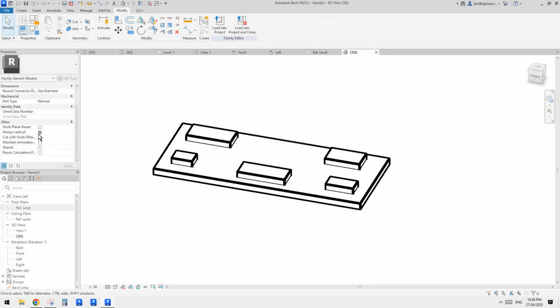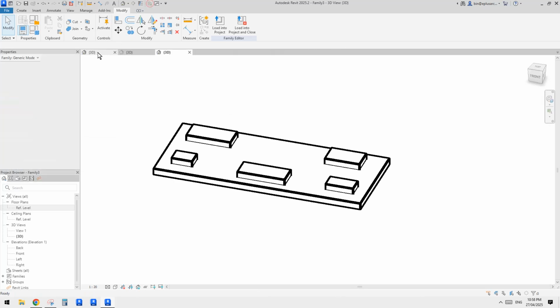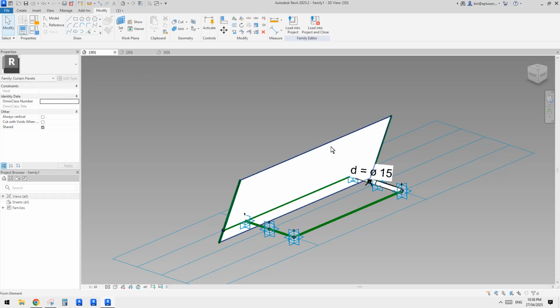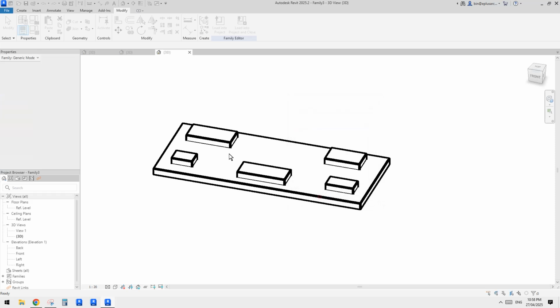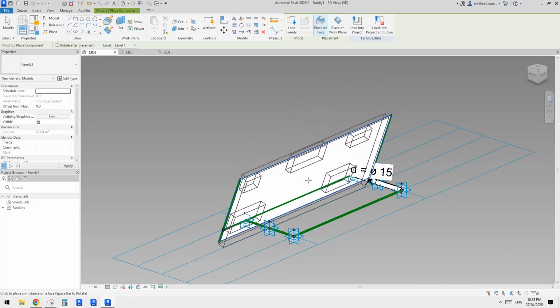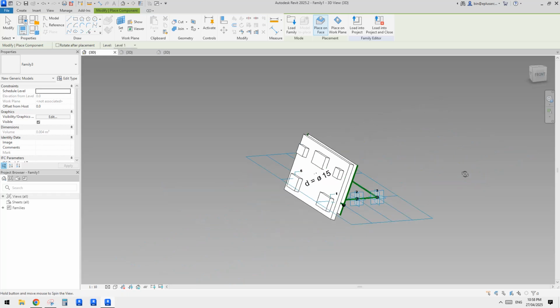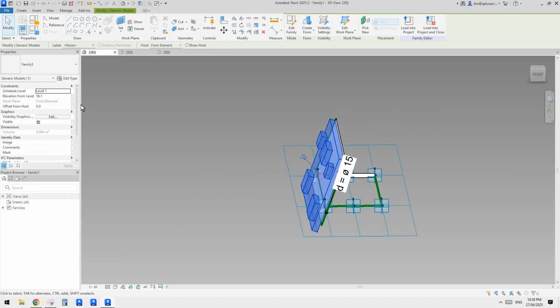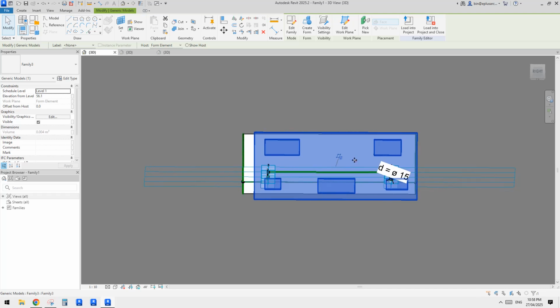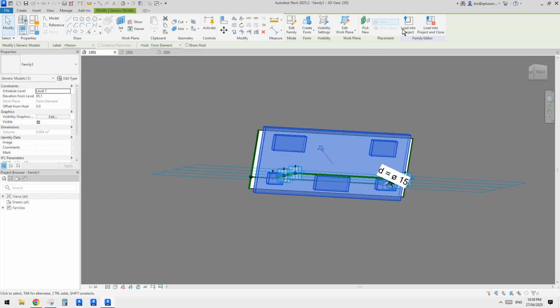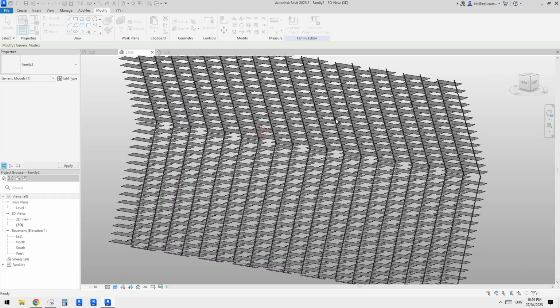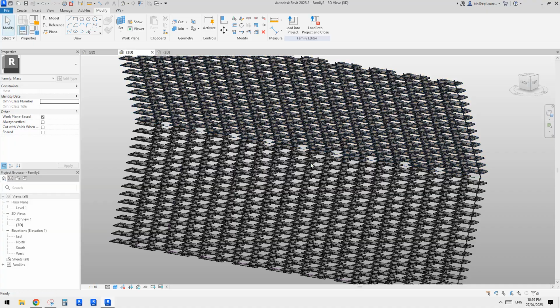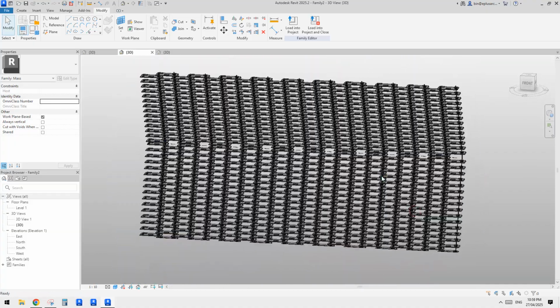Oh, hang on. I'll just untick this always vertical and tick the work plane based, and I'm going to load it into this pattern based family, which is family 1. Okay, load this one into family 1. So see, we can actually place onto this. Yeah, wrong side, that's fine, we can flip it roughly. Okay, and then we're going to load this one into family 2, which is a conceptual mass family, and overwrite. So now you will see we have something more interesting, right?